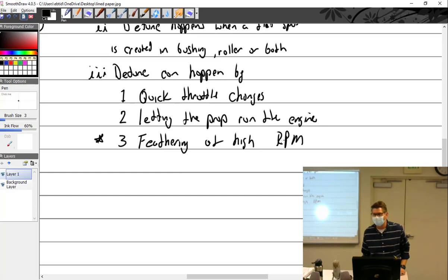I was going to say you hear that a lot, like when a turboprop comes in and parks in a spot. Oh yeah, they'll completely feather out. Yep. Now, obviously, there isn't an issue there because, well, I guess it's connected, but it's not connected in the same way as a reciprocating engine. Right? Yes, they have an opposite problem. If they didn't do that and it sat there and motored, it doesn't have oil pressure.